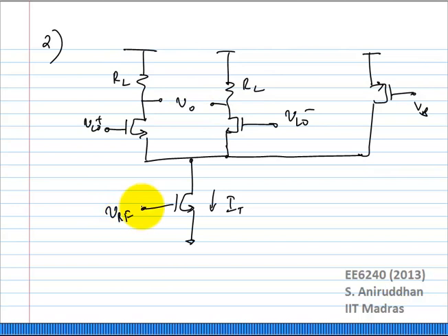Okay, so let us look at this. Suppose I add some I0 here. What are the advantages or disadvantages of this? Well, the advantage is the current source no longer limits the linearity at the output node. The output can swing as much as it used to. And you have also managed to break this connection between IT and the output common mode. Correct? So this is doing exactly the same thing as before as far as output common mode goes, but the current source is no longer impacting the output linearity. Anything else?